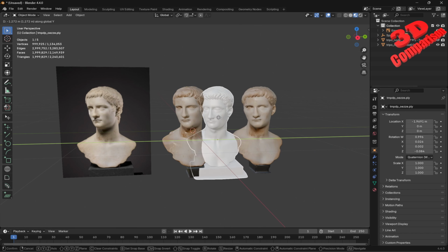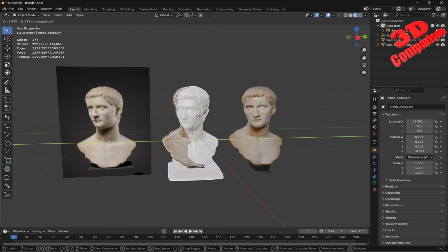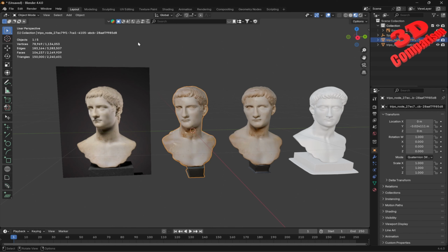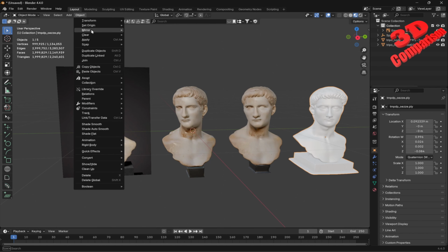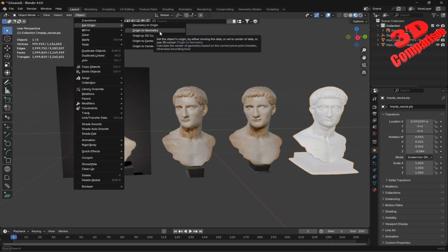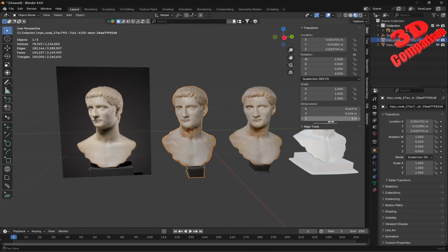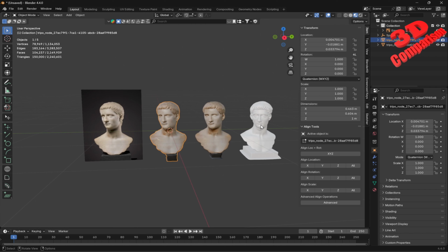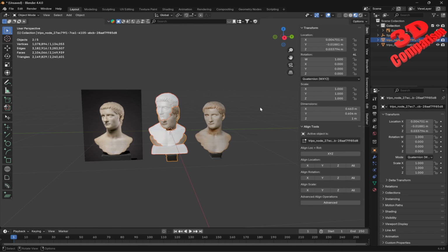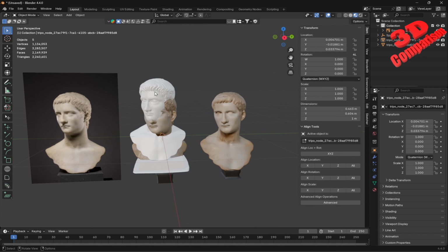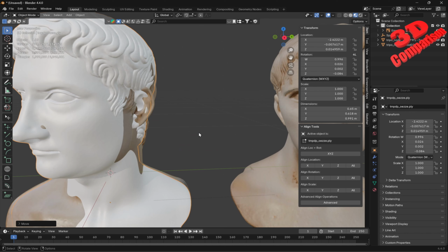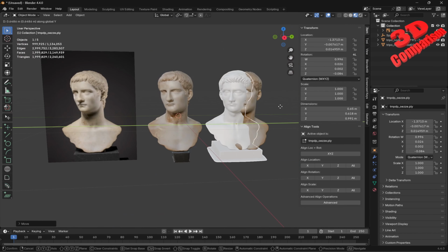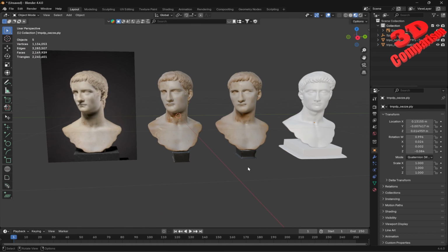since they will be quite overlapped over here. So I can select those. I can change the geometry to be straight in the middle. So origin. And now using the align tools, I can have this added exactly on top of this. As we can see, I will also need to change it on the z-axis. So maybe something like this will be close to an overlap. And we can have that baked texture transfer from one model to the other one.